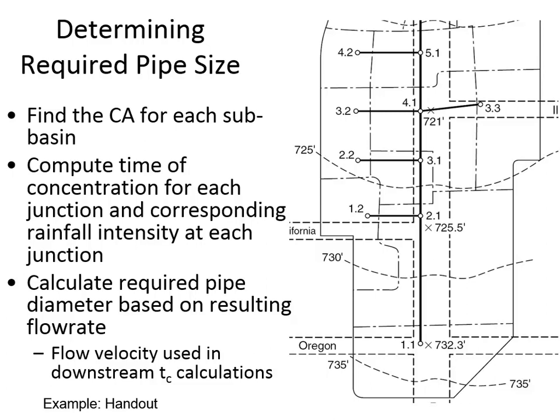So basically the calculations you do in hydraulics is for some flow rate, how big does the system need to be? What the hydrologist does is say what the Q is based on watershed characteristics. And so the easiest way a hydrologist can say what the flow rate is going to be is that rational method that we just learned. And that's essentially in 3 easy steps the job of a hydrologist. Never mind that the results aren't too accurate, but it'll get the job done in any case.